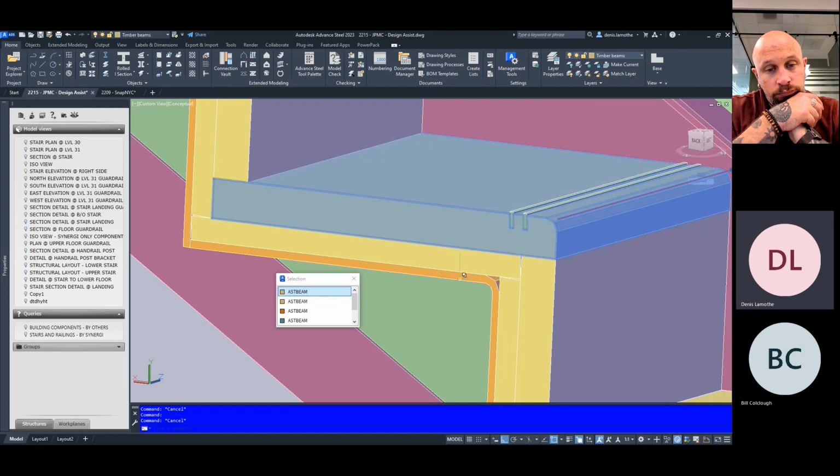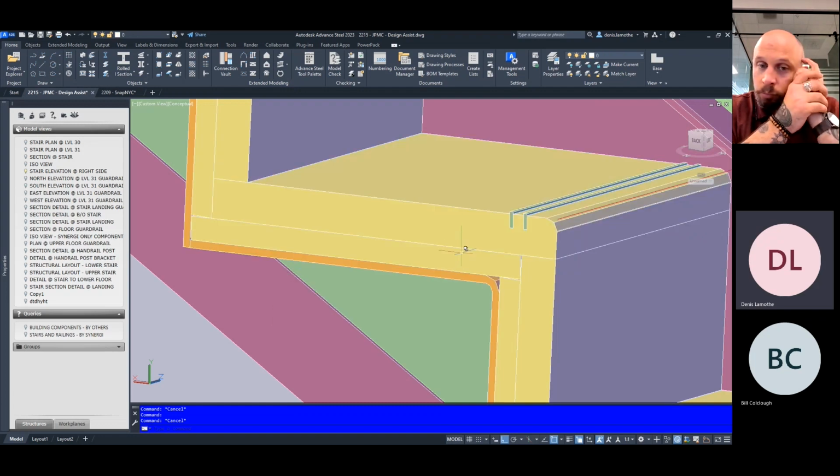That way, it's easier to attach the finish to the treads. In this case, any adhesive they're using, or a combination of adhesive and maybe some hidden nails here and there, works better with plywood. It bonds better to it than it would if it was straight up steel.